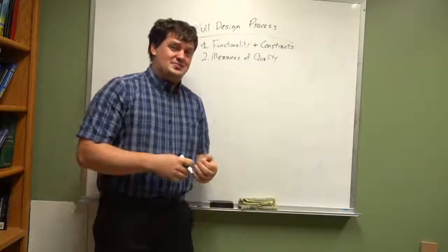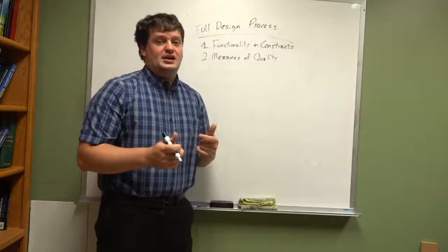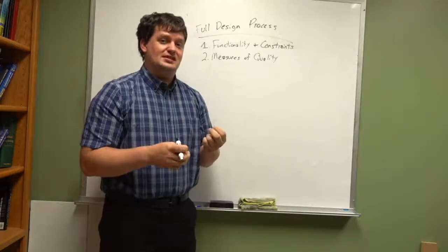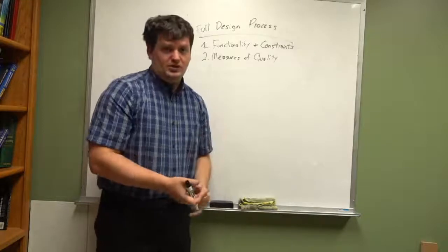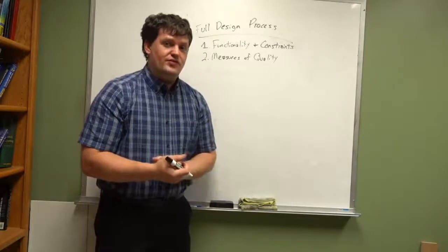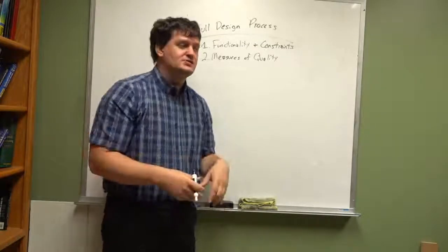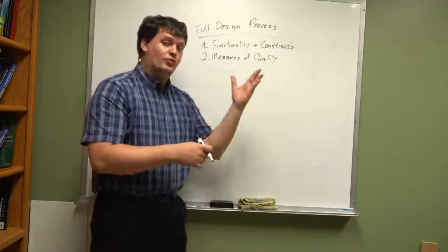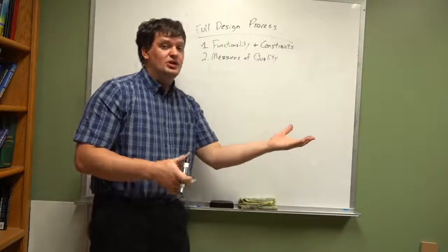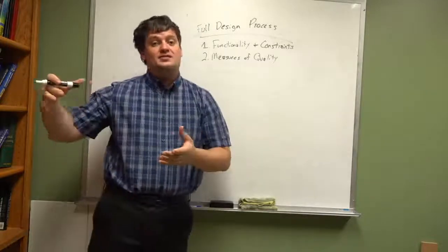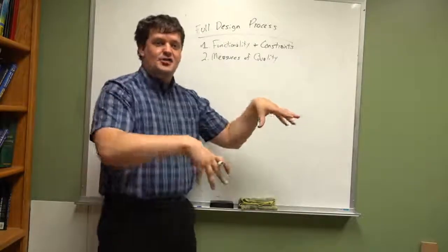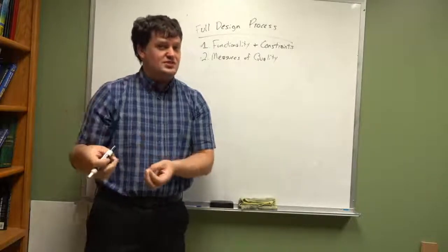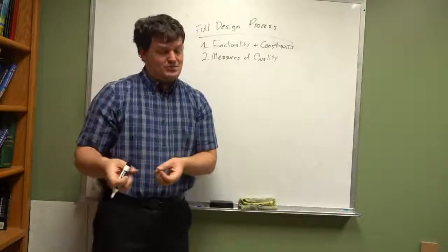If weight does matter, you're probably going to want heavily reinforced, very specially designed components that are ribbed, that have sufficient reinforcement, non-linear components, probably made out of high-grade materials. If weight matters that much, you can cut weight, but instead of a big, bulky cast iron piece, now you have a very fine-tuned, difficult to manufacture, expensive component.